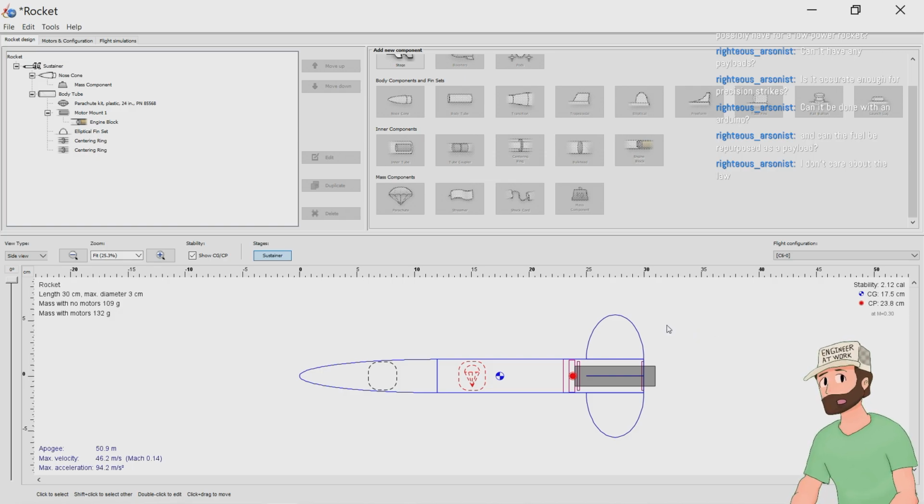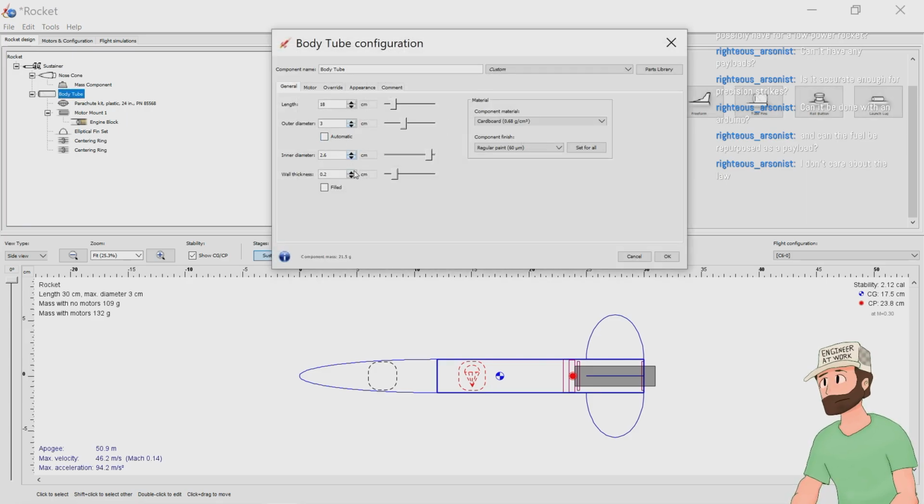Well, the easiest would be to do, if I do 0.4 to 0.7, I think I can do 0.8. Let's try 0.8 millimeters. If I use a large diameter extrusion nozzle, then I might be able to get away with it if we do it in vase mode. Let's see. The nose cone, we don't have to, but the body tube I would like. Wall thickness, 0.2 millimeters, 0.8.